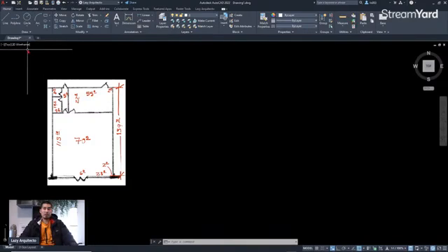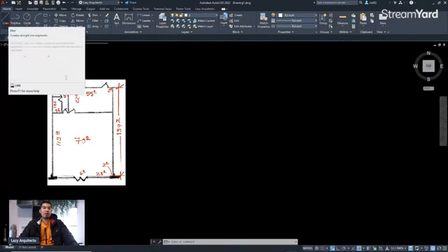Once you understand the concept of the ribbon, you need to also learn another concept, which is keyboard shortcuts. Keyboard shortcuts are very important. Whatever command is on the ribbon, let's say the Line command, if you hover over it without clicking anything, you'll see some instructions: the Line command creates straight line segments, and so on.